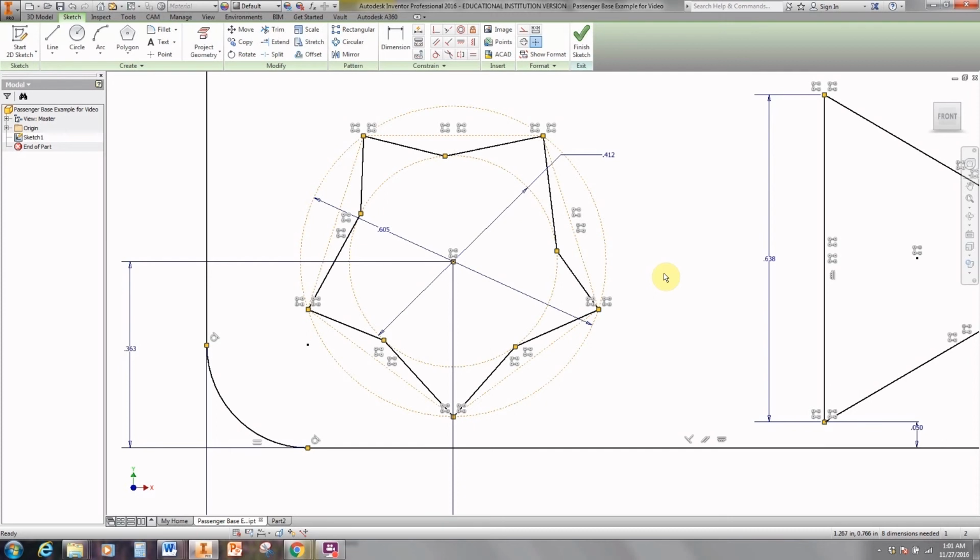So we say, show us all the constraints. And we look around, and this looks really good. All we have are these little guys showing the coincident points. That's great. Sometimes this line will show up as vertical. If this line shows up as vertical, that's no good. You have to delete the constraint that says it's vertical. You don't have to delete the line, just the constraint. Because if you delete the line and then redraw it, it's going to be vertical again.